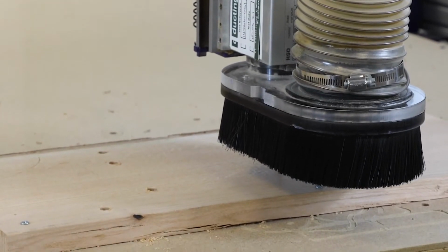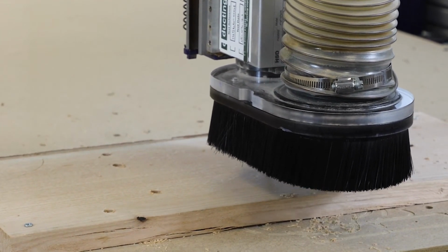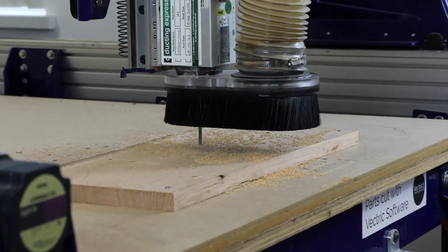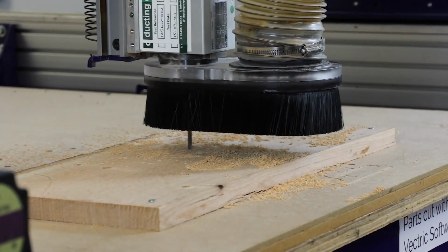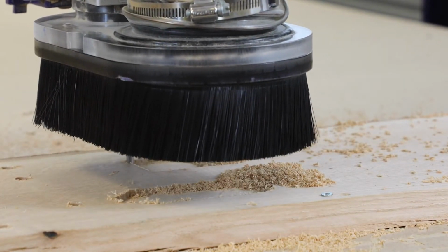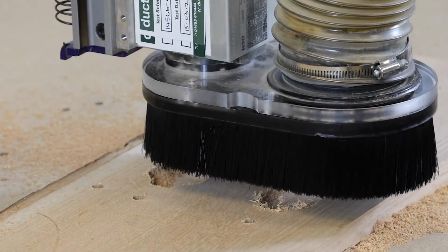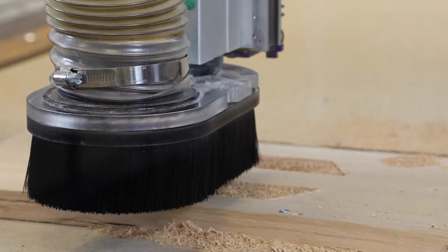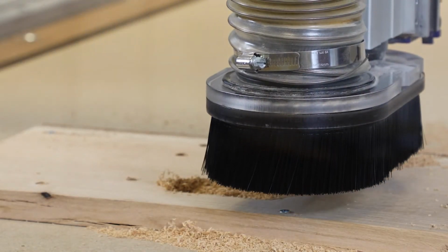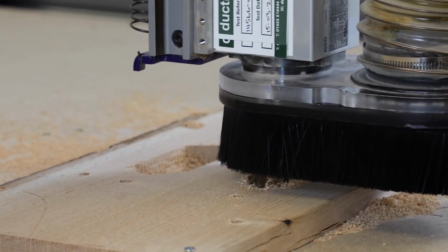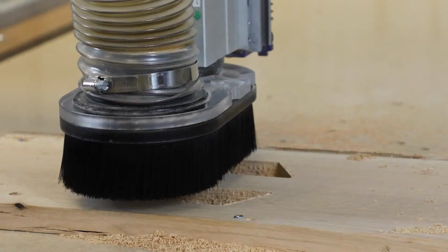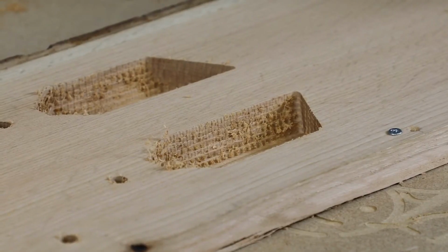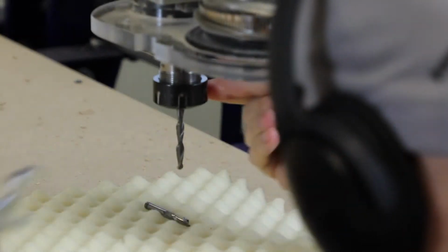Then we're going to go in and start our roughing pass for the inside of the bottle. And I've chosen to go down level by level, so you'll see that it will go down the pass depth of my tool in one of those pockets, or one of the insides of the bottle, and I'll move on to the other and do the same, and it'll jump back and forth between each bottle side. You might want to adjust that depending on your needs, but I felt removing the material evenly from both of those pockets might lessen the amount of stress that would be relieved from my wood at one time, or at least make it even.